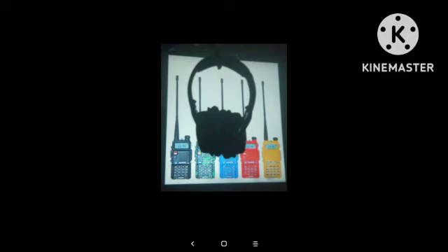Number 45. A dipole transmitting antenna placed so that the ends are pointing north-south radiates mostly to the east and to the west. Number 46. What is the low-angle radiation pattern of an ideal half-wavelength dipole HF antenna installed parallel to the Earth? It is a figure 8 perpendicular to the antenna.